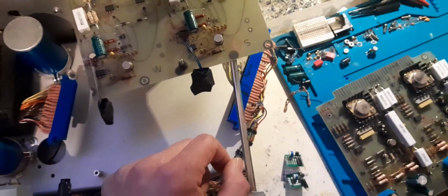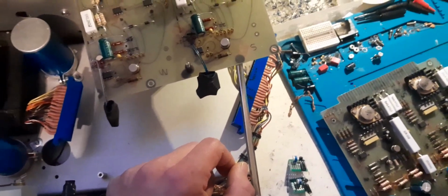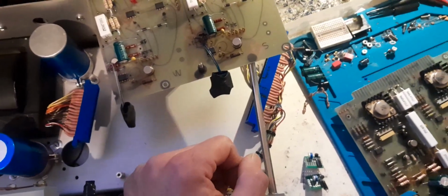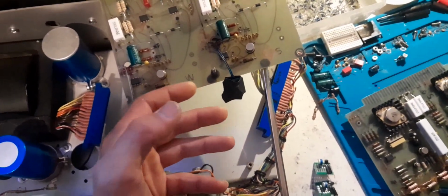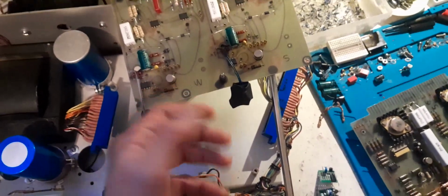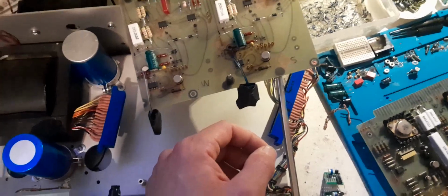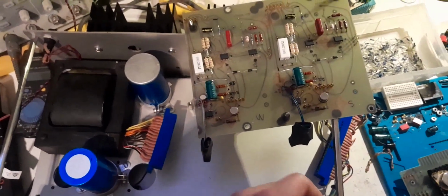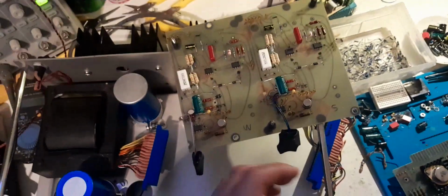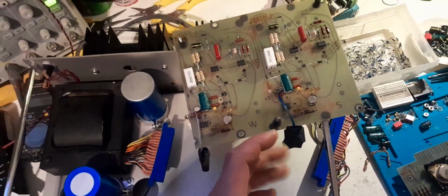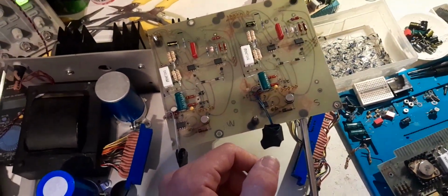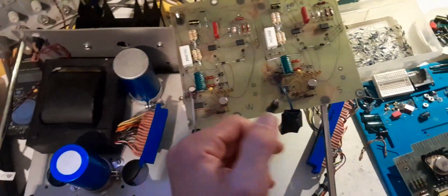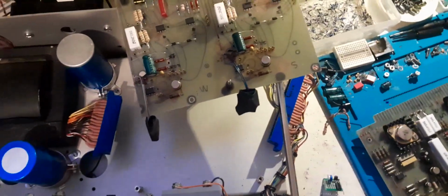I mean, honestly, there's not even really any point, because from what we've seen, whether the Zener's in there, the reference is in there, a better compensated reference is in there, the oscillation's obviously coming from the constant current circuit op amp. So now we know what works out best in this thing, we might as well do that to all of them, like what I just said to the bottom 2 and what I propose to do to the top 2.